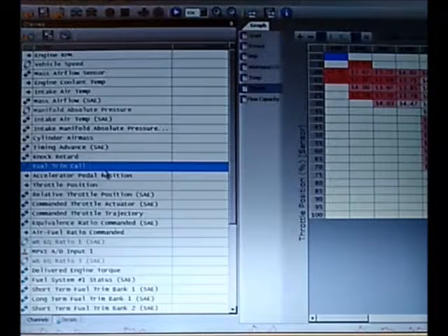Sometimes you can use this to filter your data instead of the way I did it, which is to filter by torque and throttle position. But I don't trust fuel trim cell because it basically breaks up the VE table into quadrants and numbers them. So if a cell falls in a certain RPM and manifold pressure range, it gets assigned a number.